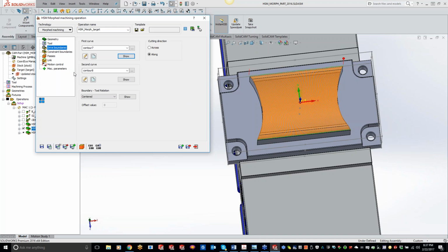Okay, so what Jason is saying here, I'll just read it word for word: the toolpath that generates looks very nice, but from my experience using a ball end mill, it gives you that center of the ball mill has 0 surface feet and tends to drag and leave small little chip fragments embedded into the part. I'm curious if anyone else has found this to be the case.